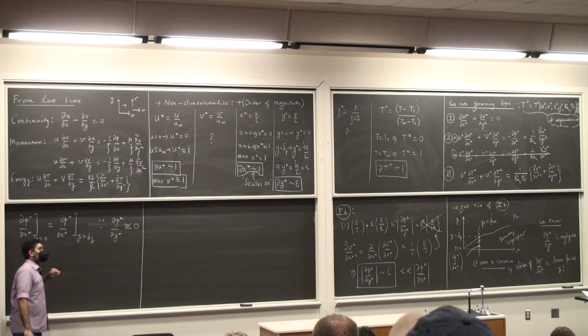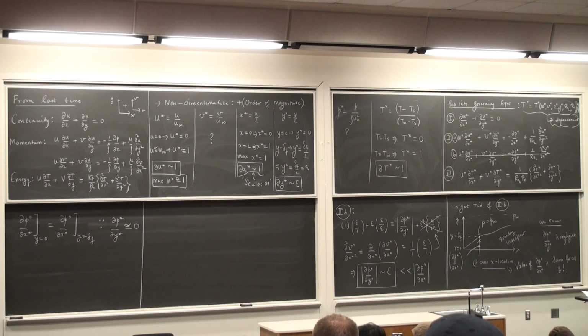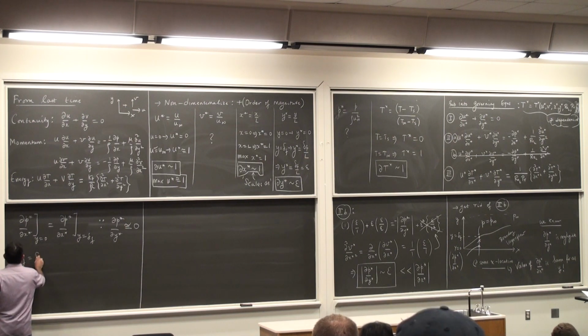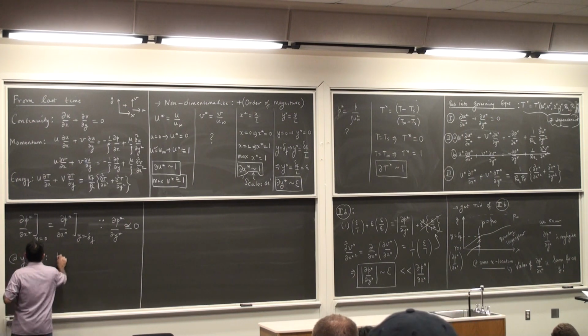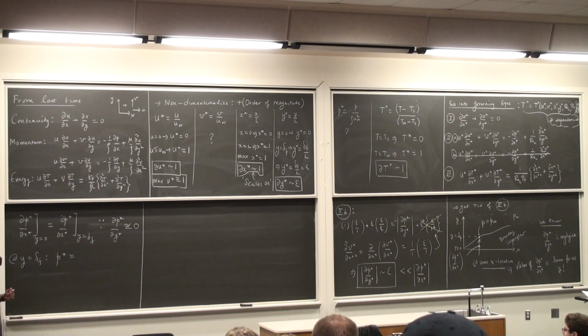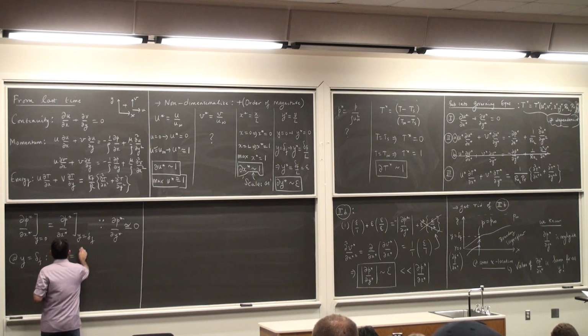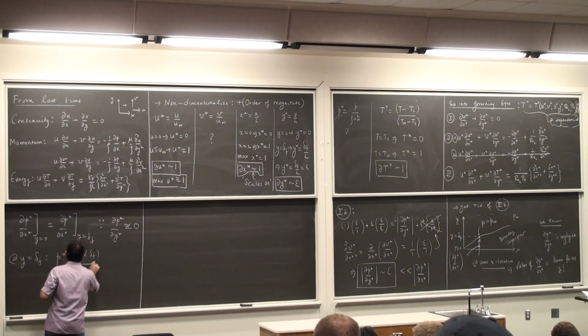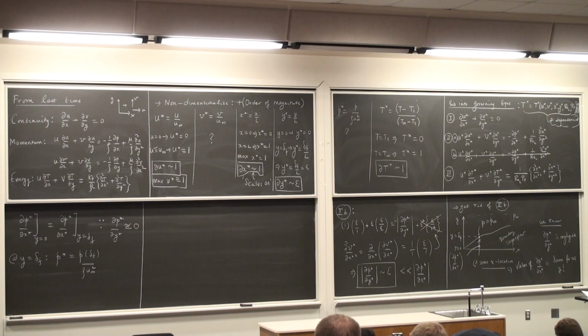And this is the big leap that we're going to make. We've made many leaps. At the edge of the boundary layer, what is the pressure? At y is equal to delta f, P star is the pressure at delta f. Rho times u infinity square. I'm just copying down the expression from the first panel up there. Okay. What's the pressure at the edge of the boundary layer? This is just P infinity.